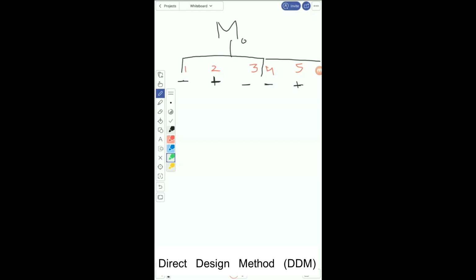If you remember, these 3 values we have calculated using a case, and these are the typical values. In the third step, we have to do the transverse distribution, like we have to distribute this moment at A in this direction. Similarly, if you are asked to do the transverse distribution for moment at location 2, or maybe you may be asked for transverse distribution of moment at location 3. So once you are doing this transverse distribution, what you are basically doing is distributing the moment at A into what goes to a column strip, and what goes to a middle strip.